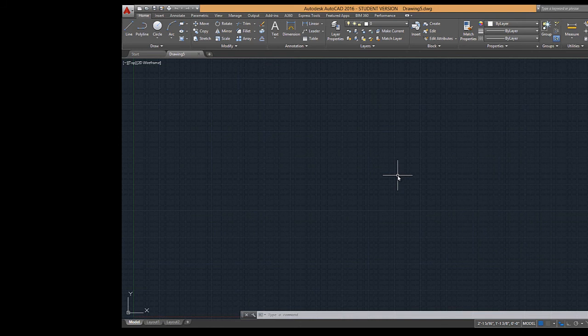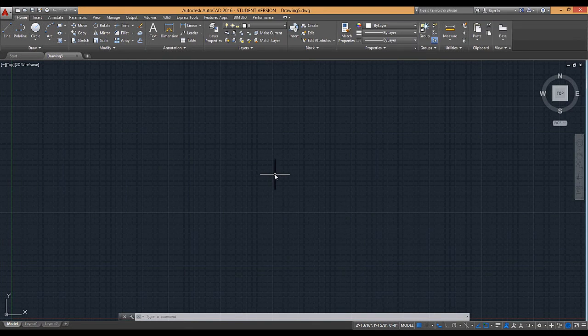So what I want to do is start to draw objects on layers. So if you wish to make a certain layer the default layer, there's a couple ways of working. You can start off by, if you know that you're making walls, making your default layer the wall, so that everything that you draw is automatically going to go on the wall layer, and you can change them as you change what you're drawing. Or you can just start by creating them all on one layer and then reassigning them later on. Just keep in mind that you can only have one layer current at one time.